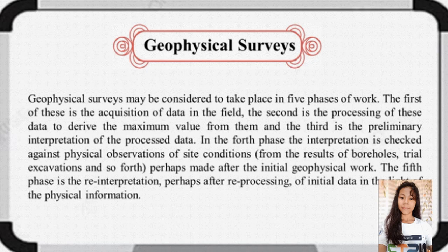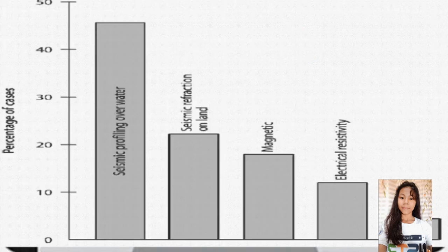significance. When geophysical results are compared with records of boreholes, it does not necessarily follow that an apparently incorrect geophysical boundary must necessarily be corrected to fit the borehole record. The boundaries seen geophysically may not be those seen by the eye in borehole samples. This is a figure of an analysis made by Higginbottom, which shows the relative popularity of methods at that time in Great Britain.